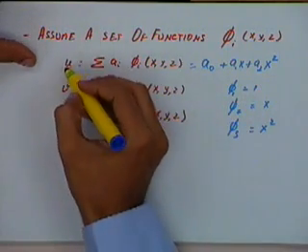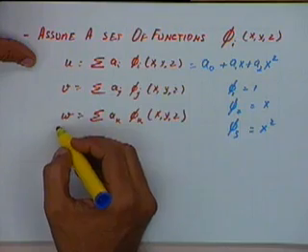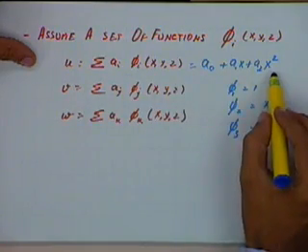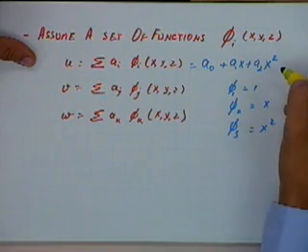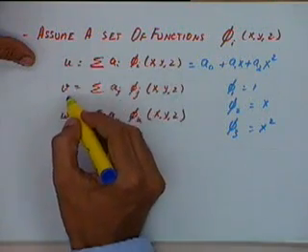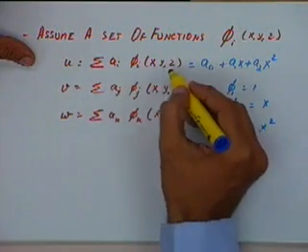So in general I will write down u, v and w using similar expressions like this. I can assume it to be a quadratic function, I can assume it to be a higher order function, or I can assume it to be consisting of some other type of function. So I will assume that the deformations will be given as some function of x, y and z.